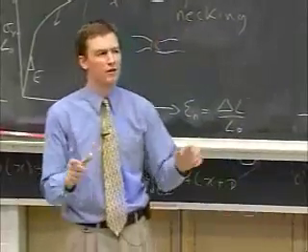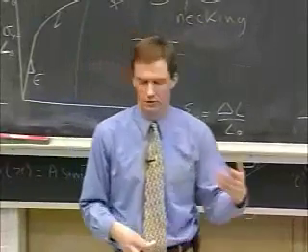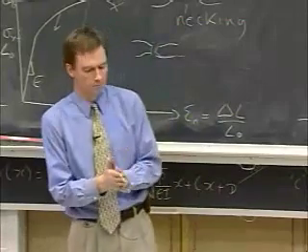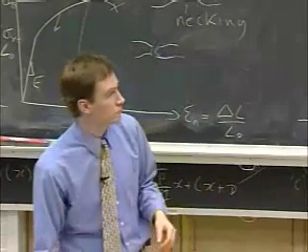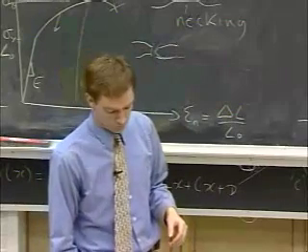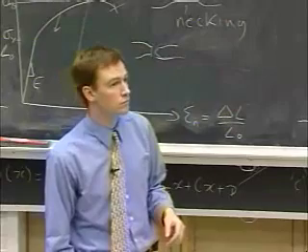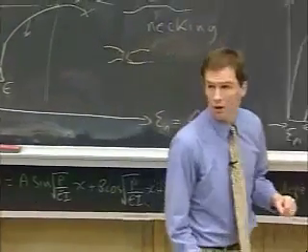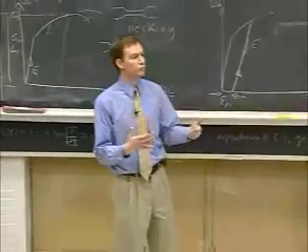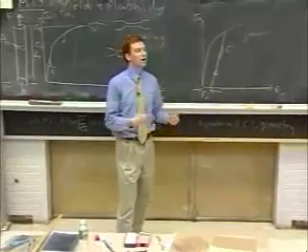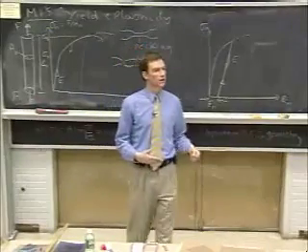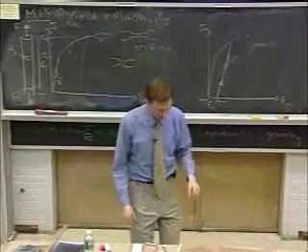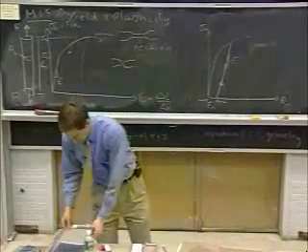Tempering. There are some other things going on in metalworking steel. There are phase transformations, which we're not particularly going to talk about here. Yeah, Ben. I was curious about why the curve dips down after the maximum stress. We'll come on to that. Basically, it's run out of work hardening capability. You can't make it any stronger. So failure starts to occur. We'll look at that, hopefully before the end of this lecture.